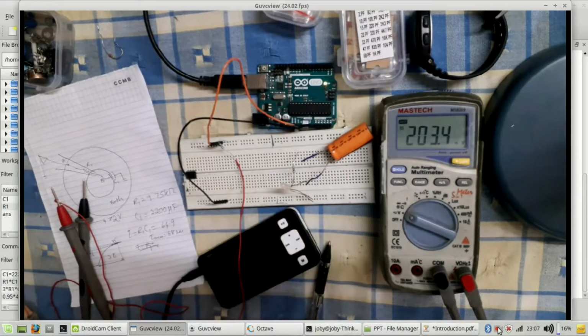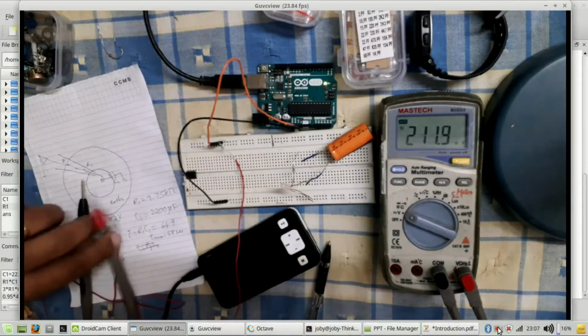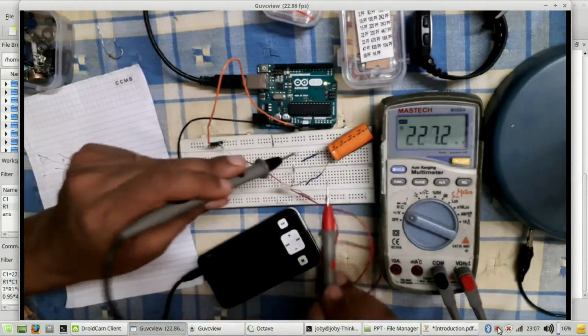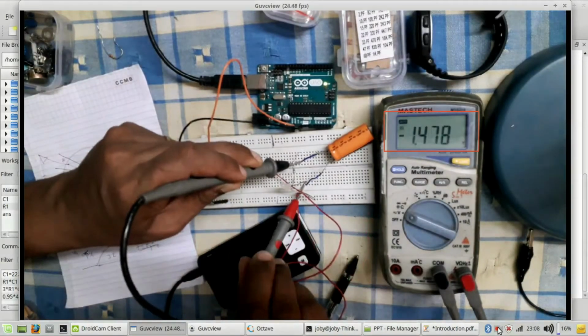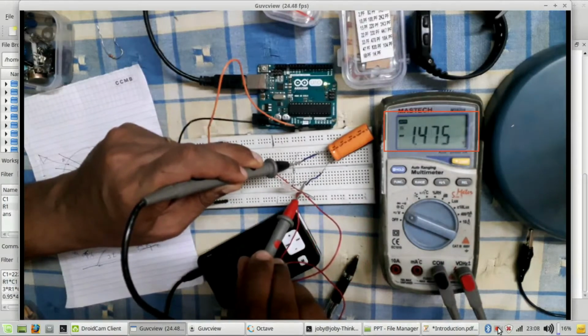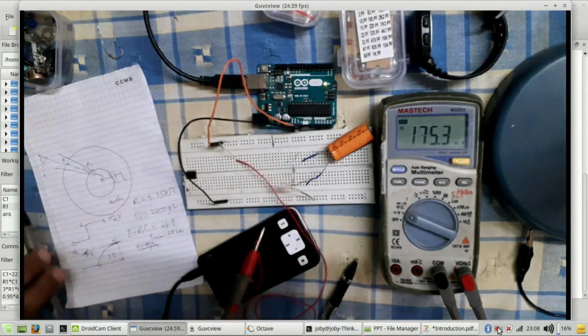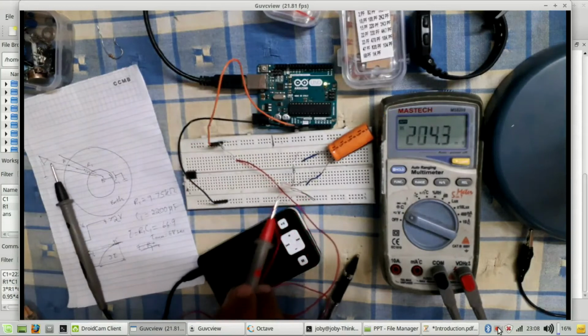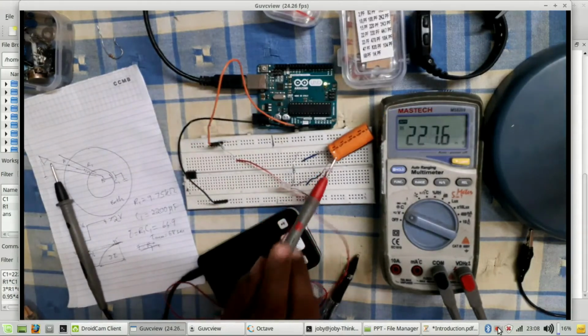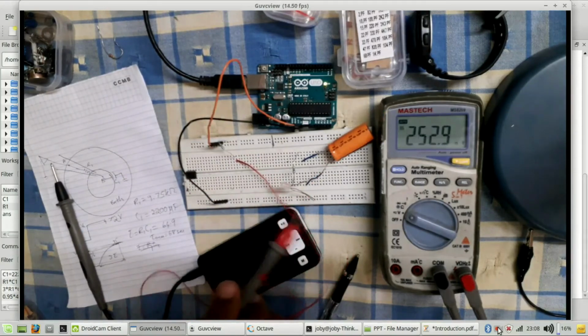Now the voltage across the capacitor, if you measure, it should be nearly 0. Why is it not 0? Yeah, because I have not used the normal incandescent light but an LED. LED has a cut-in voltage of 1.5 or so. So after the capacitor voltage has decreased below that, there is no voltage to drive the current through the LED. So that would mean that the capacitor will discharge up to the cut-in voltage of the LED.